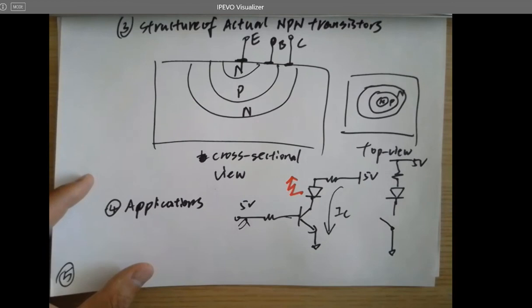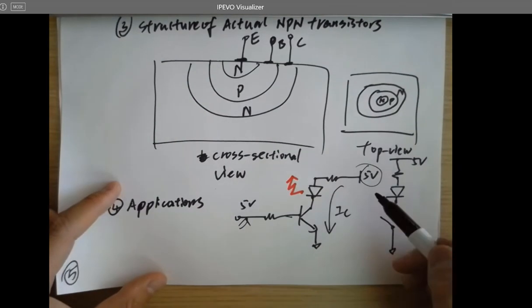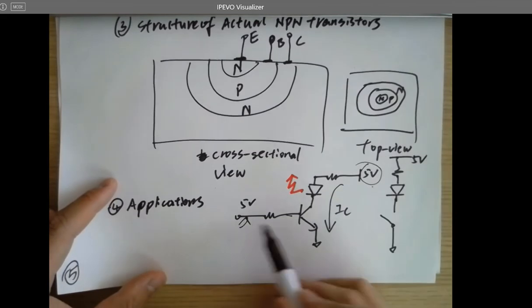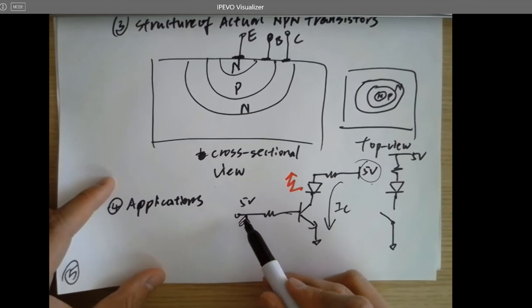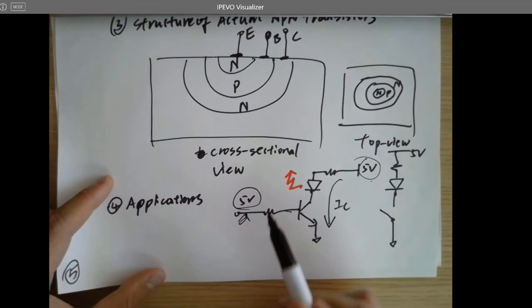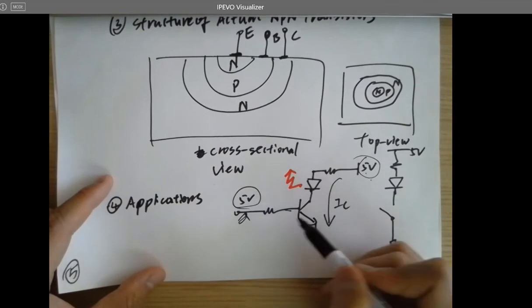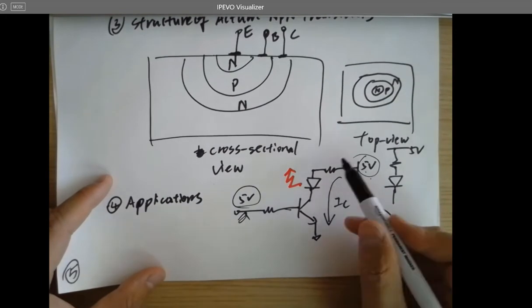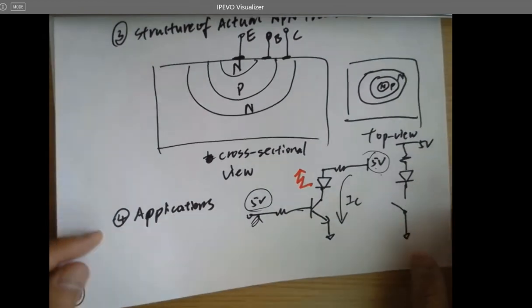High current, yes. So sometimes the motor is being driven by like 20 volts, and you just need a low power and fast digital pin to turn on, turn off this channel. And 5 volts definitely cannot turn on, turn off that motor, so you have to use a switch to indirectly control the motor. If this is 20 volts.